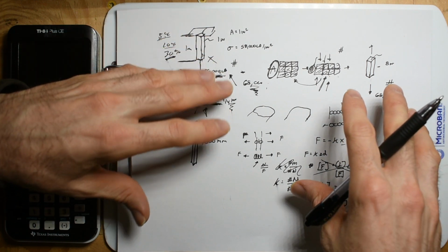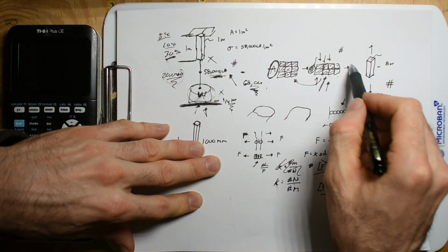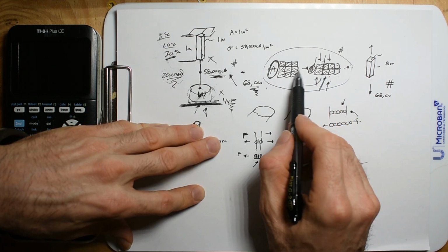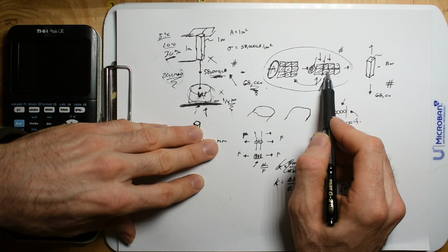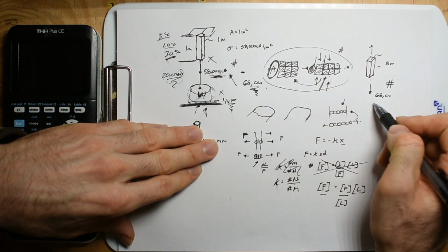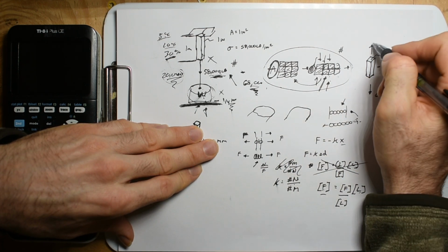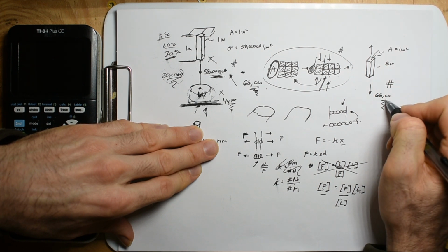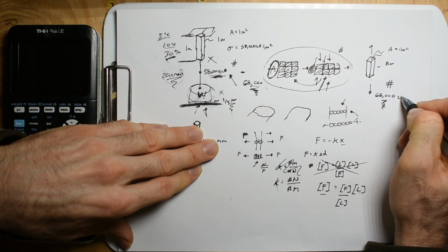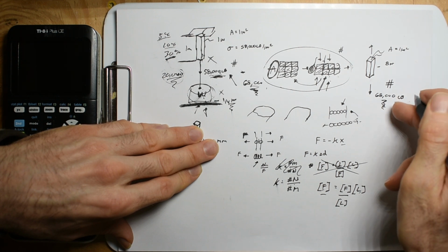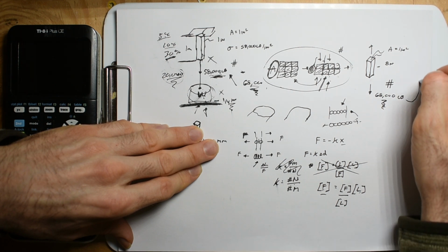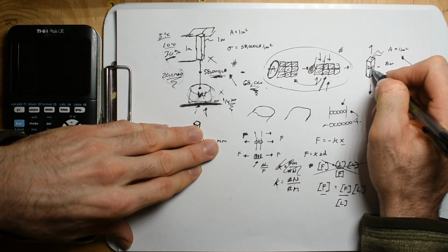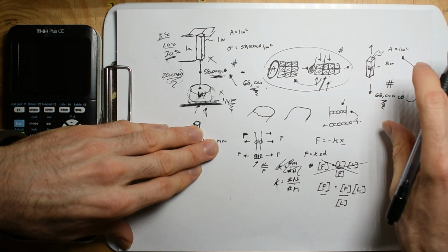And almost all of this, it is good to know what's happening at a molecular level. The other thing is that at the molecular level, because we are getting this extra strength, and this area is going down, on our readout, we just knew that this surface area was 1 square inch. And then on our readout, we're getting 68,000 pounds as our max force, and we're just assuming that area is 1 square inch. Well, no, this thing necked down a lot. The surface area didn't halve.